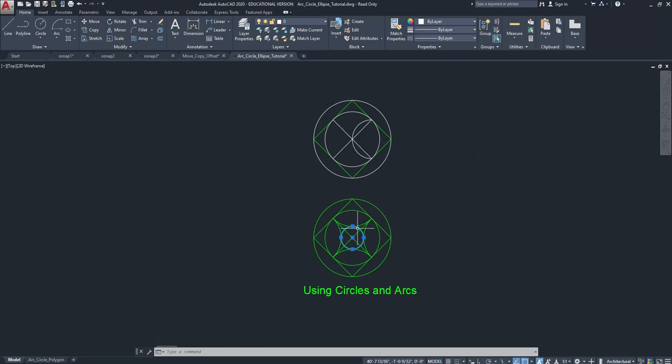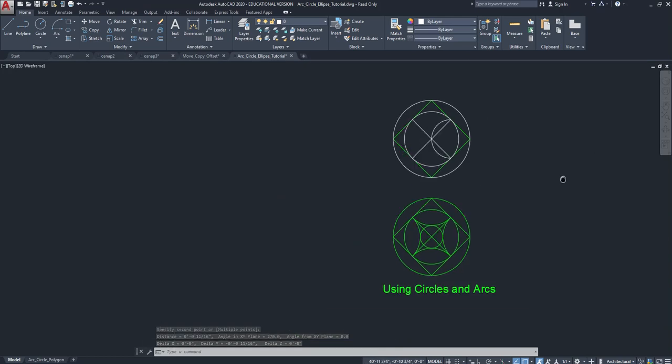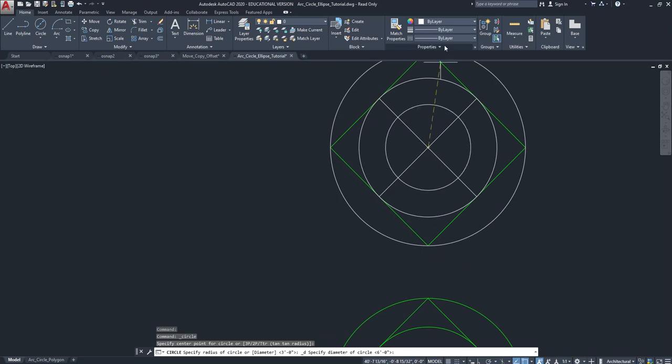Sorry, I don't actually have my circle drawn in here, do I? I'm going to do distance, and I'm going to measure this circle, DIST. That circle is 11/16 in diameter. It's a little bit of a tricky dimension to input. Circle. Let's do a diameter, center diameter. Click. And my diameter is 11/16. That's a good input to learn. Enter.